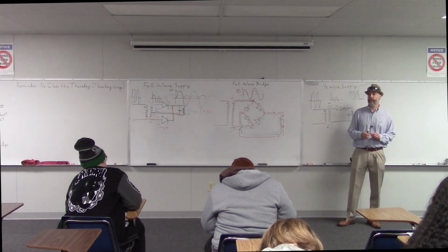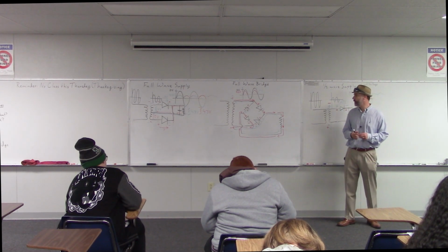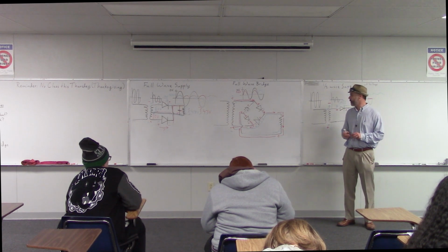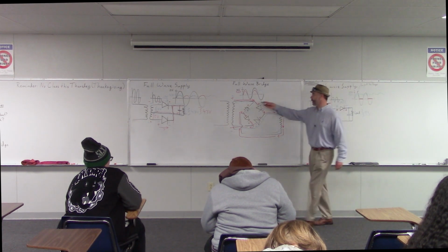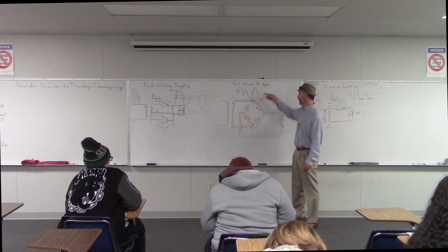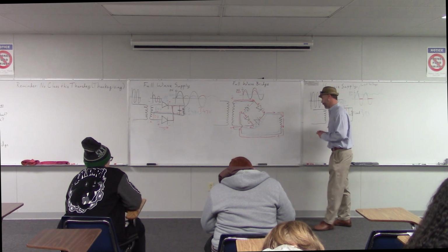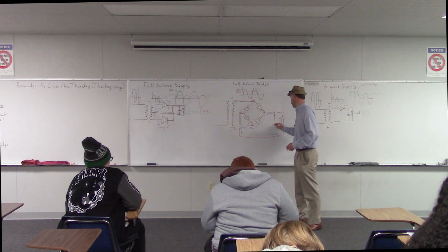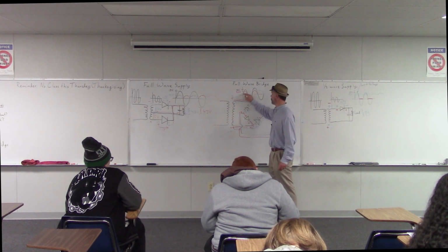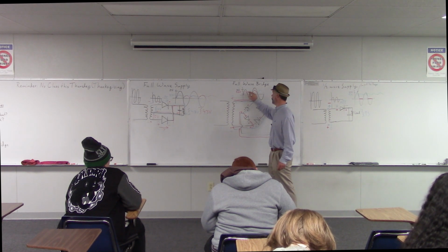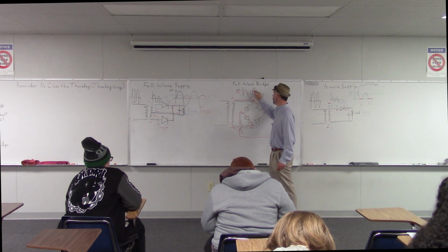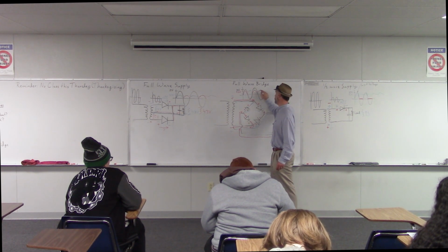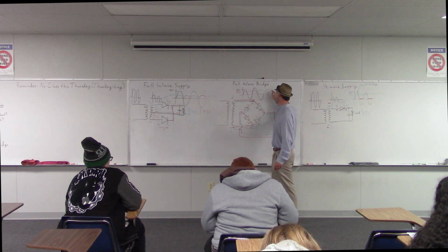Yeah. Other questions? So no capacitor? Again, this is kind of what the signal would look like without the capacitor. When we actually build the circuit, we would put in a capacitor to smooth things out. And then when we do that, it does what we've seen before, where we end up with the capacitor charging up and then discharging slowly between the charging cycles.